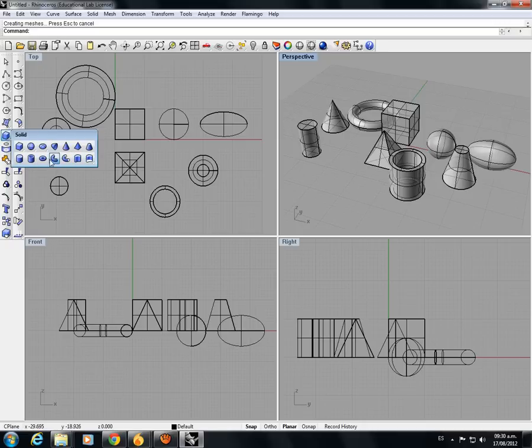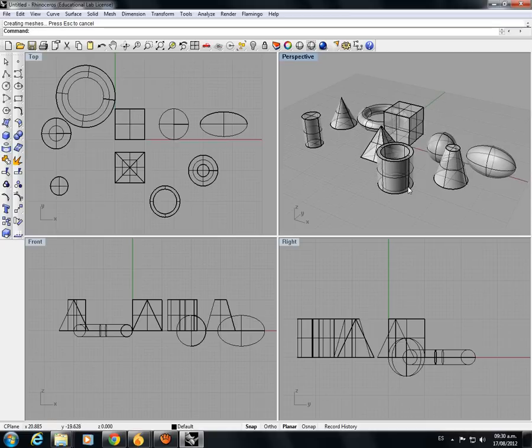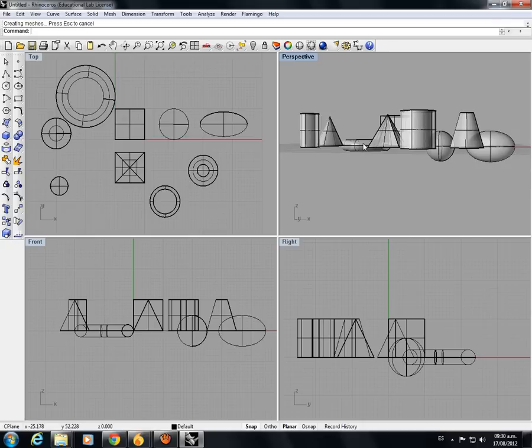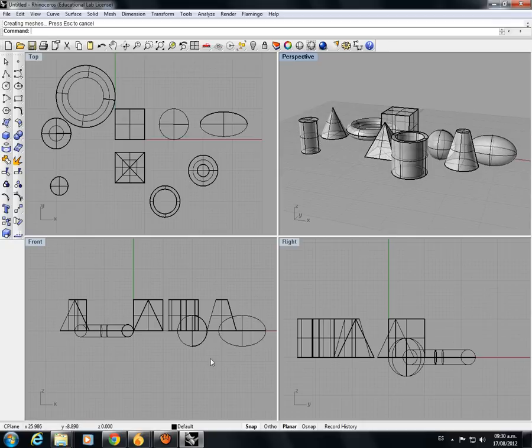The rest of them use the curves that we mentioned before. You can always play with curves and try to see what these options are for. Now, the combinations of these solids will help you create new objects. Now, the only thing that we're missing is that on the front view, as you can see, the sphere, the ellipsoid, and the torus have half of their object underneath the ground. Underneath the ground is like when you look at the ground, half of them are buried. So we need to move them.